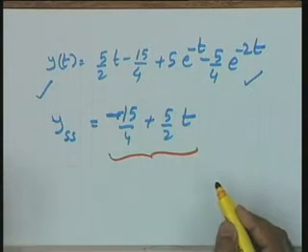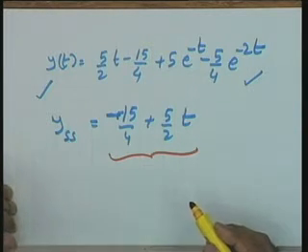The final value theorem gives the result as infinity, while the basic time response analysis shows you that the steady state response of the system is given by this expression, minus 15 by 4 plus 5 by 2 t. The steady state on the time axis starts as soon as the transients die out. So, this is the expression, and this expression naturally as t tends to infinity goes to infinity. So, the two values will match at t tends to infinity, but the total steady state expression is not given out by the final value theorem in this particular case, because sY(s) has a pole at the origin.